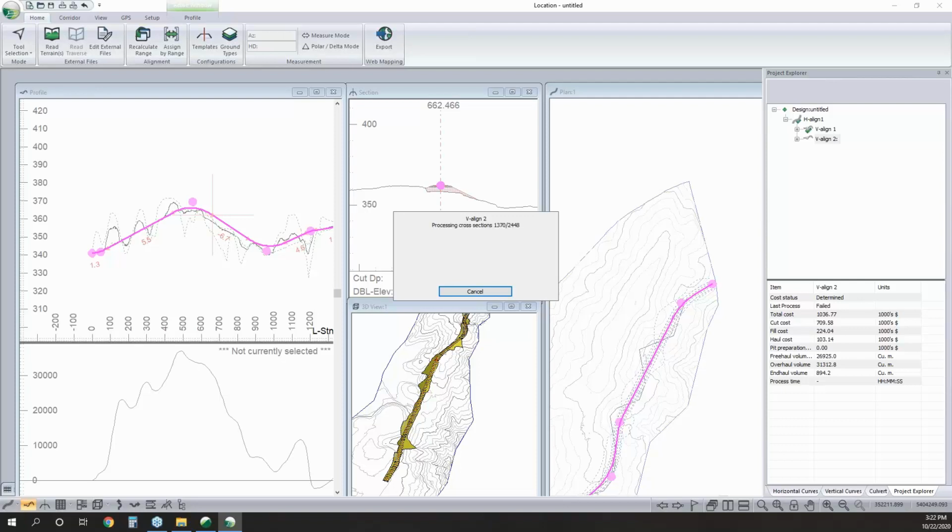Yes, you can. So there's a couple different ways you can do that. I'll explain it a bit more here once we've finished calculating the optimization. But by default right now, it's just optimizing the cost for subgrade construction. So that's, in most cases, if you're looking to optimize your alignment, that's what's variable. Usually your road's a set width, so from figuring out the best vertical alignment, you don't really have to account for those fixed costs. But if you're looking for that for costing the project, you can add it in.